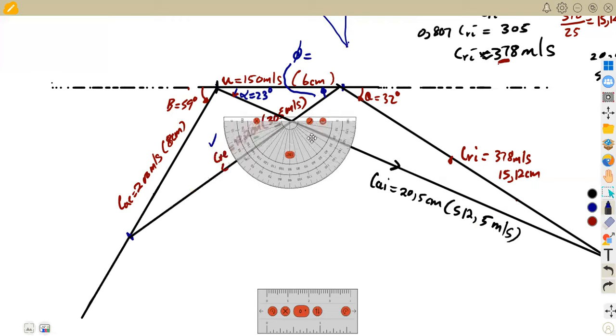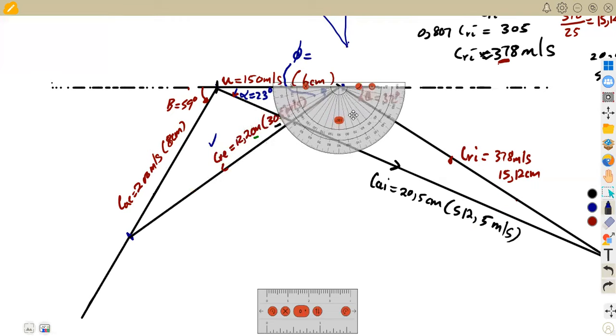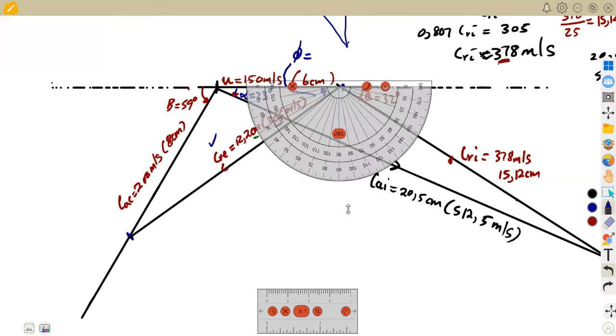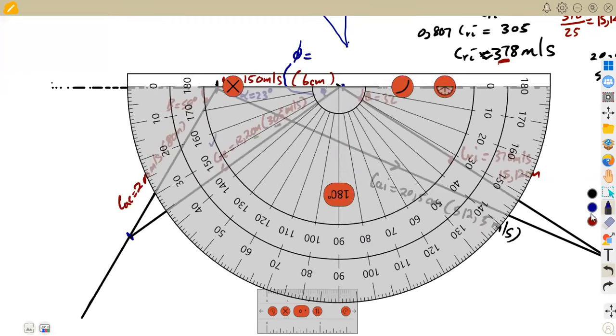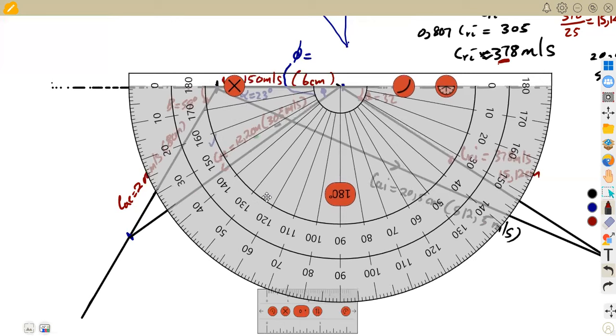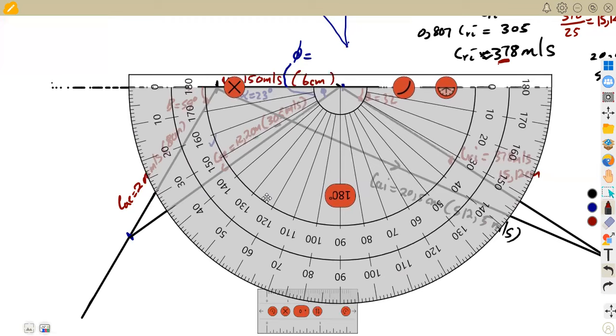So we are going to place our protractor again at this point. We measure, but this time in an anti-clockwise direction. So you need the angle up to where it reaches this line here. Where it is reaching the line, that is where we are going to take our point. Make sure it's directed at this point directly. So according to this point, the angle that I'm going to have here is 35. But the actual angle there was supposed to be what? At 34 degrees, all right?